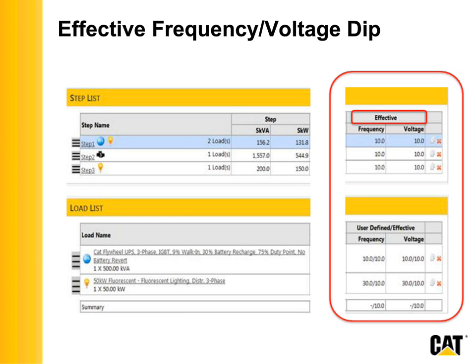If you need to do that to align with your spec, okay, but if you don't have to, multi-sequence your load steps. Have more than one. In addition to that, make sure that you sequence your loads that have the tight or the restrictive frequency dip or voltage dip later. Okay, and here that's all we're doing is showing you that again.